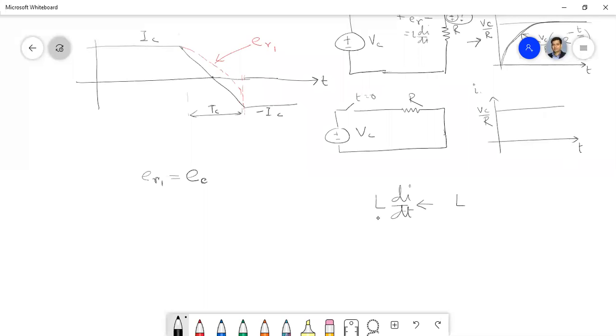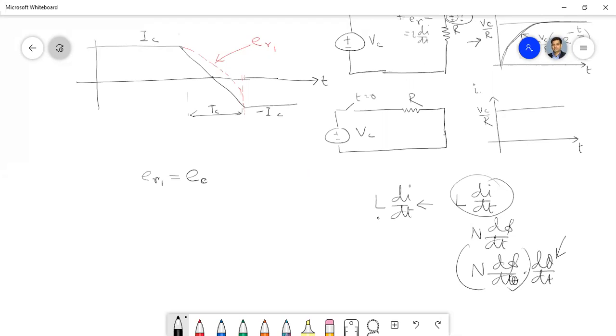But in rotational EMF, how do we get this? Relative motion between the coil and the field. Correct. So that means we don't write this. We generally write it in terms of N dφ/dt, and from that we write N dφ/dθ and dθ/dt. Okay, so here your velocity, or the angular velocity, comes. So this is how you get the rotational EMF or speed EMF.